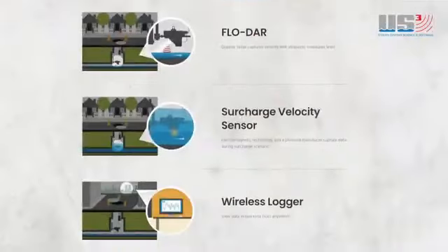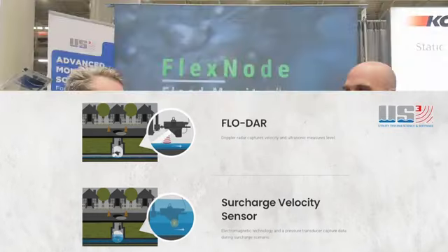So we use a Doppler radar. It could be flat in that channel. It could have a huge pitch, and that's kind of the point of your site sheet. Right. And so it's just going to be different. It's very different. And so as part of our calibration process, we also use a secondary calibration sensor. We spend a lot of time just on calibration, making sure that the instrument is reading what we really believe it should be reading. So calibration is the big one.